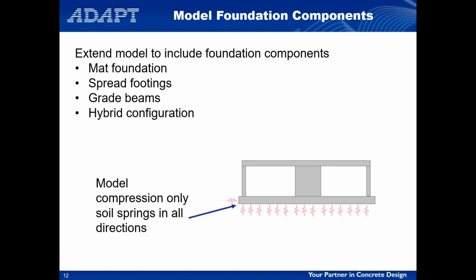So you're kind of stuck with this challenge of, even if I'm using another finite element program to do the PT design, now I got to take all of those forces, the hyperstatic forces, the redistributed dead loads, live loads, and bring all of those back through the columns and foundations. This becomes even more complex when you have mezzanine levels or a double level podium, and transfer those forces properly into the vertical component as well as the foundation.